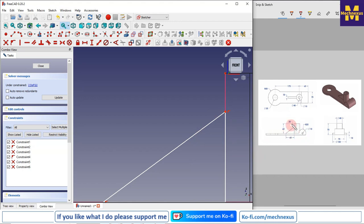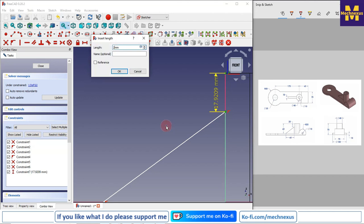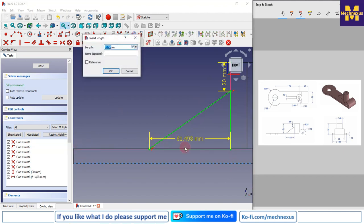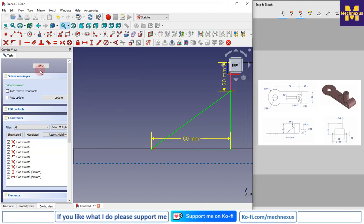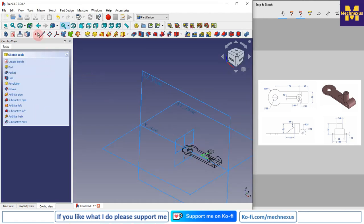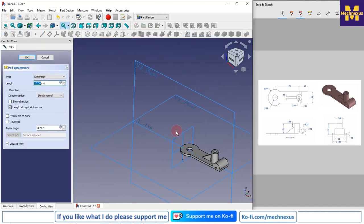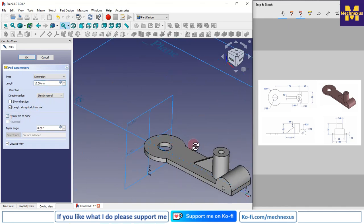So from the top it is 20, so I will select this point and this point and I will give my dimension 20, and the bottom one should be 60, and I will close it and I will move to the flat lines, and now I will say pad and I will say it's symmetric to the plane.